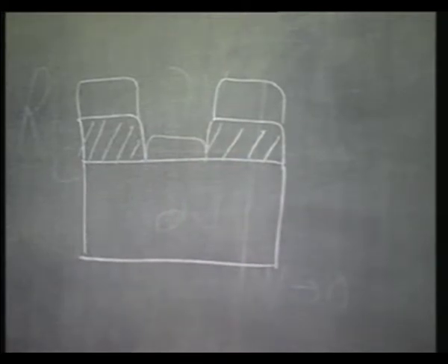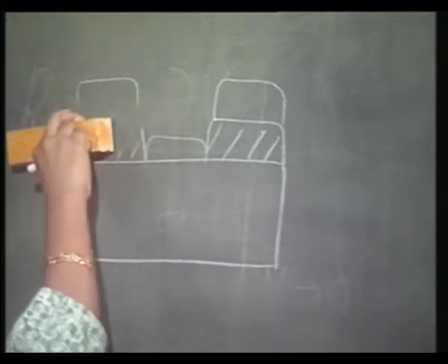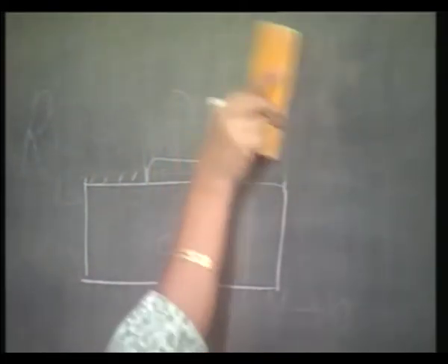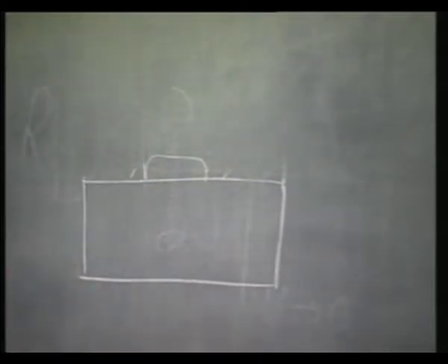Now, you have used positive photoresist which can be easily dissolved by using acetone. So, if you now put it in acetone, the photoresist should go from here taking the overlying metal along with it, and from here, leaving only the metal in this region.